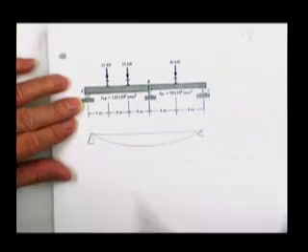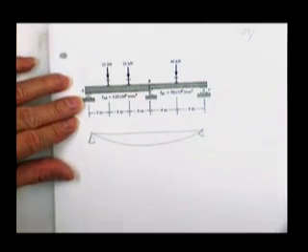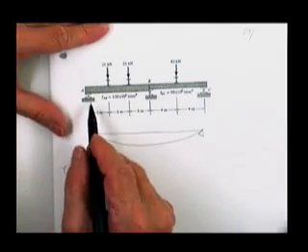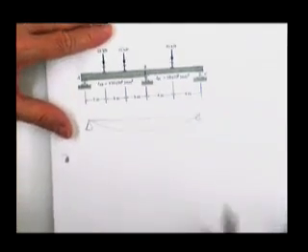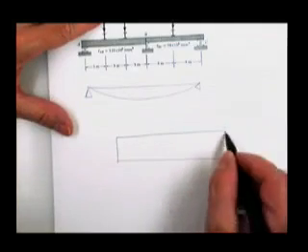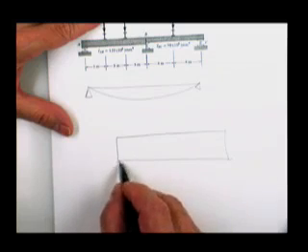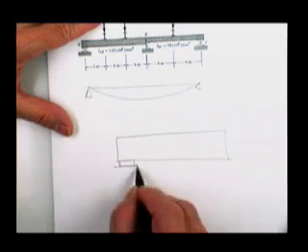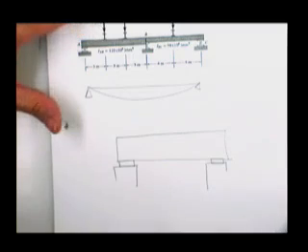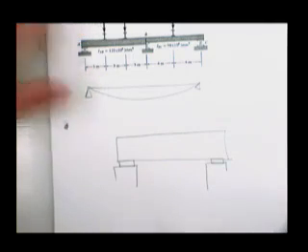And if this one also has no resistance to horizontal motion, well, we got a problem here. Somebody somewhere ought to tie this thing down. I will admit that real concrete beams out on the highway, there's such massive weight on them, they just stick them on a neoprene pad and they don't go anywhere. But one of them is going to have to be considered a pin, the other one's going to have to be considered a roller.